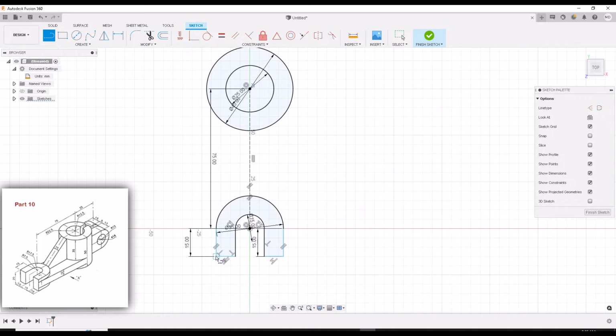You could just go from this intersection here with the line segment, make sure it's a solid line, drag it out, and drag it to the tangent of this OD, and then do the same thing here, drag it out. It's going to snap. There it is. It found the tangent. All right. So that was the first step.